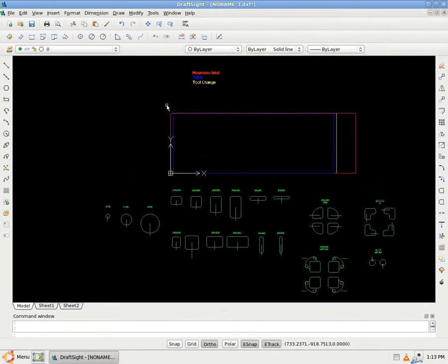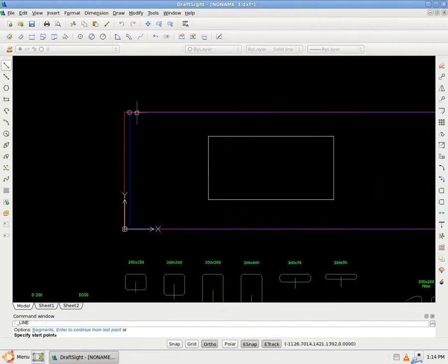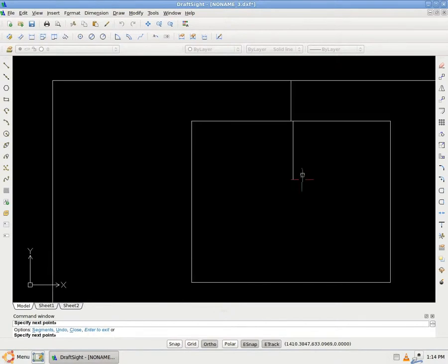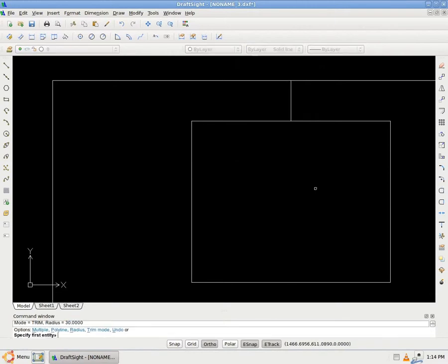I will now draw a small bathtub inside my working space. I'm drawing the perimeter of the stone I'm going to use for this job. I'll now draw a sinkhole. You can draw a new sink, or copy and paste one of your saved sinks. When I draw my sink, I will always make the start and the end lines overlapping. If you do it too, you will not feel where the machine has started your job.